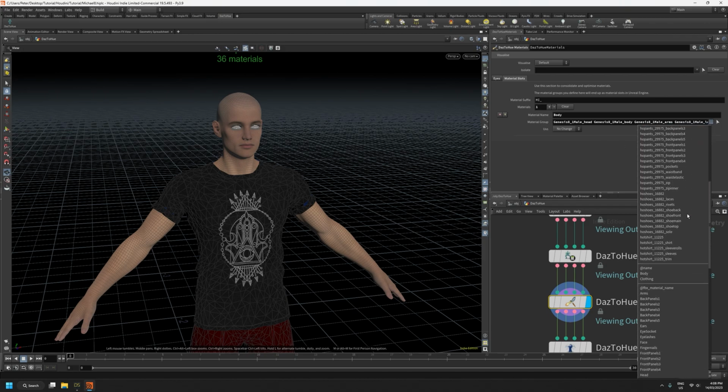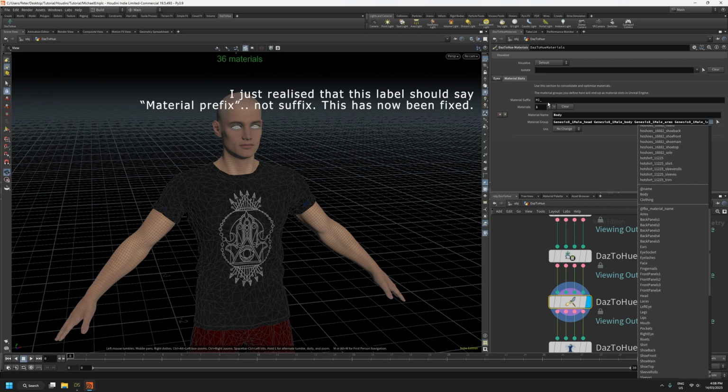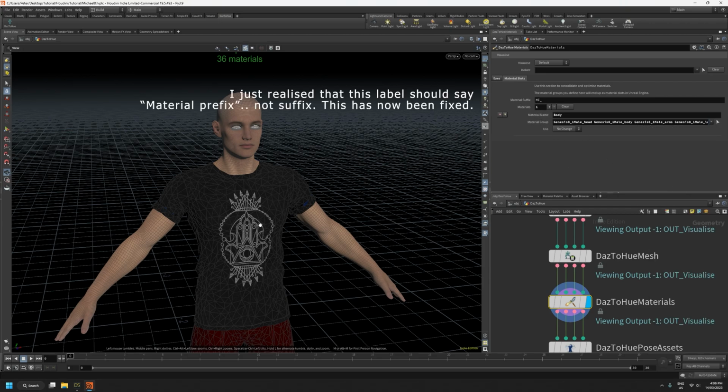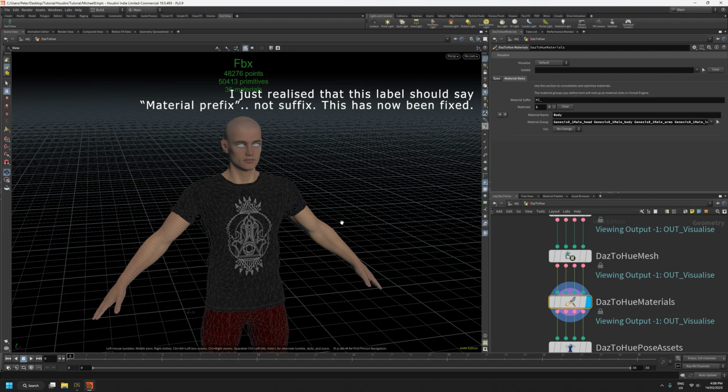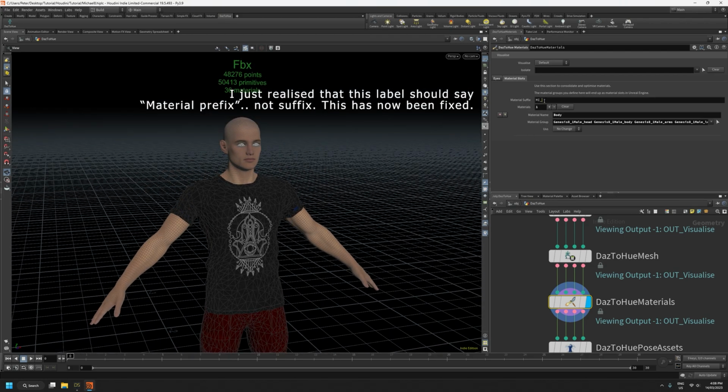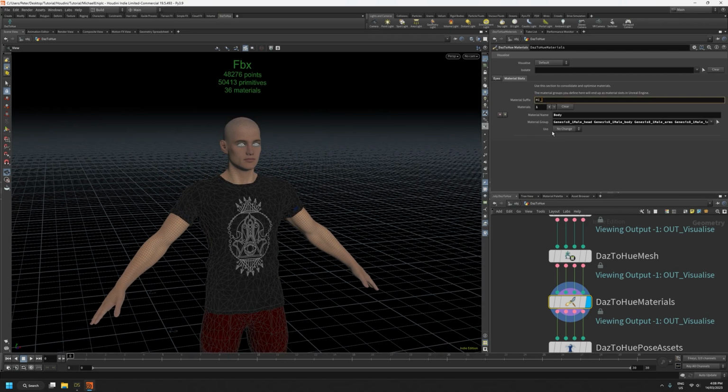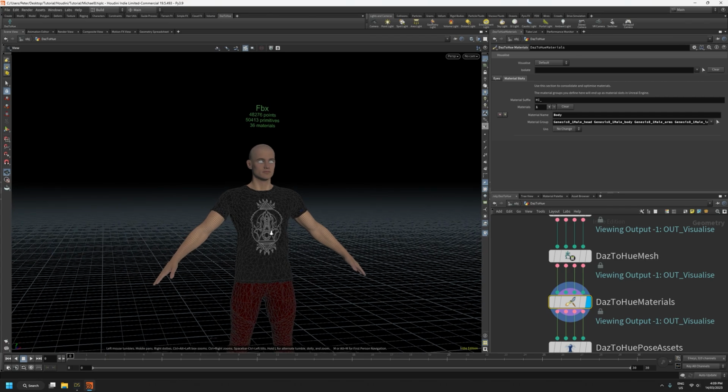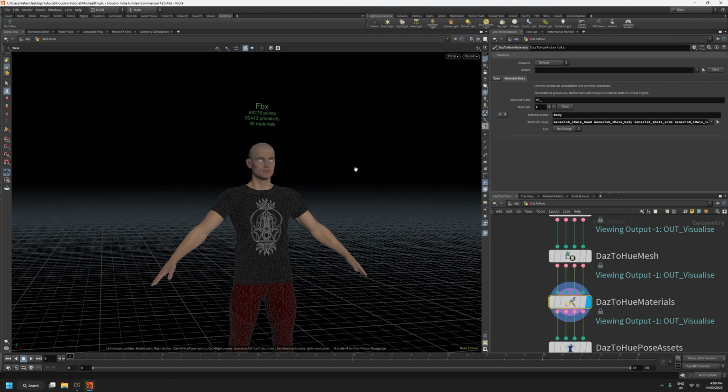You'll also see it's prefixed it with this material suffix. I always work with material instances inside Unreal Engine, and I give those an mi_ prefix. If you have a different naming convention, you can change this to whatever you like. So, as I say, I pack those textures into a single 8K texture. And to replicate that, I have this option to change the UVs for this material to a 2x2 grid.